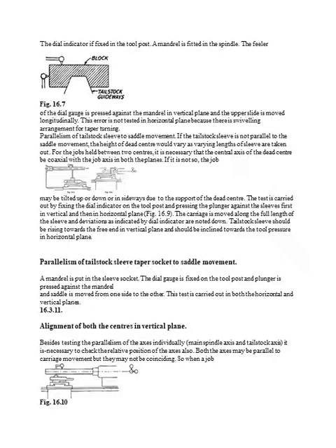Over that we place a dial indicator, and it is moved along the top surface, and similarly on the vertical side. So both will show the deviations of the tailstock guideways.